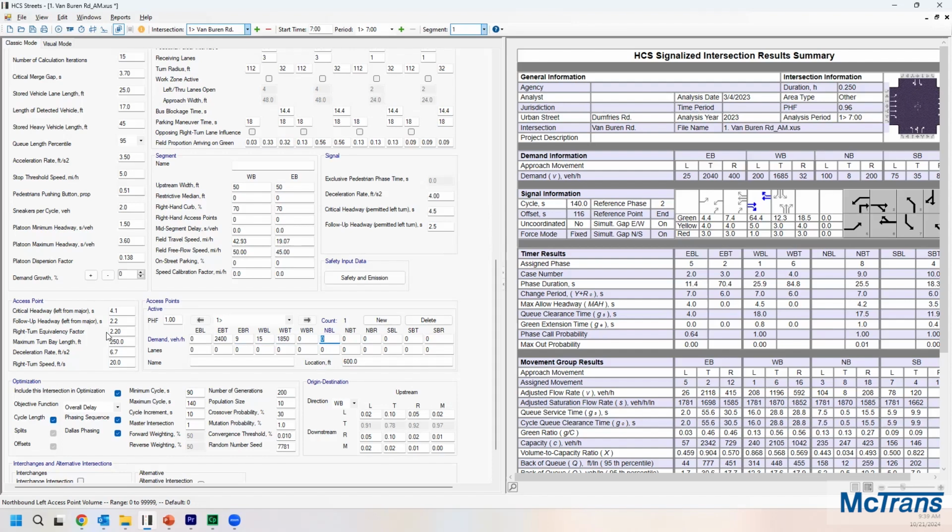northbound left 13, northbound right 127 vehicles per hour. There's no southbound approach here. Let's also enter the number of lanes. Number of lanes is important because turning movements can typically add more delay if you have less lanes.